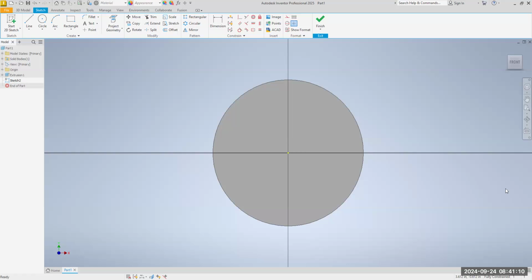All right. So what I need for you to do, we're going to draw a circle, but it's for construction purposes only. We're not going to keep it. So go to circle, select circle center point, move your cursor to the origin. See how it turns green? As soon as it turns green, click and drag out a circle here. Now, what is the dimension again?